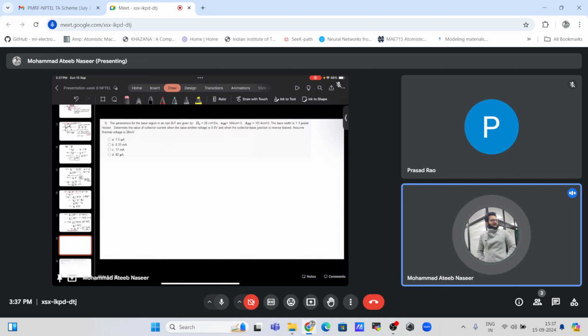The collector region will have a larger depletion width compared to the base and the emitter, and as a result of the reverse bias the field will be high, so the carriers coming from the emitter into the base will be directly swept to the collector.